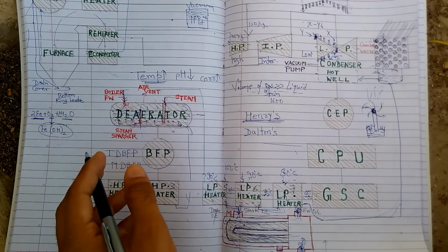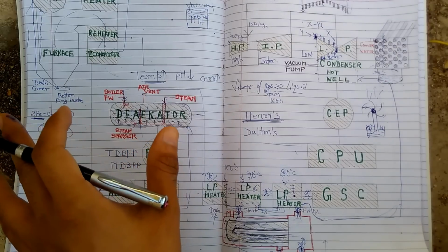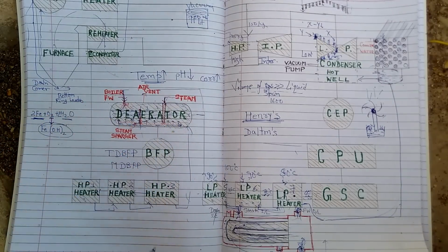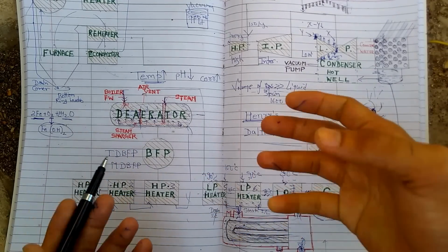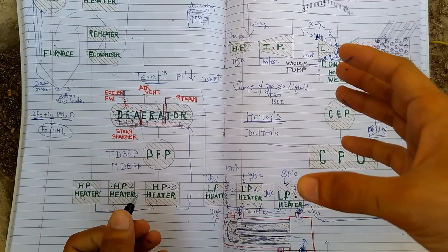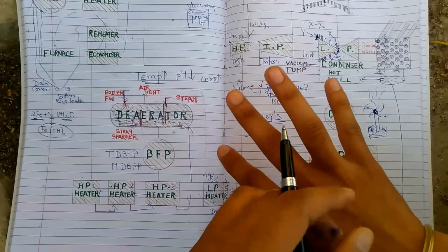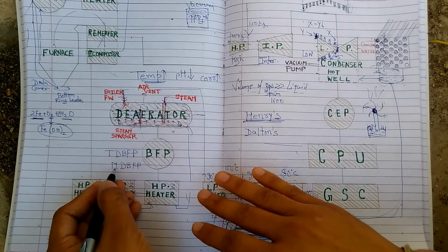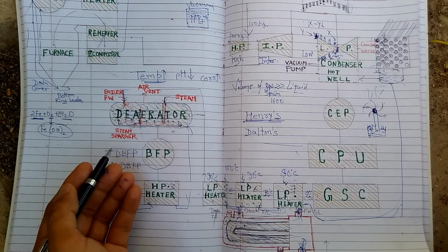Now I have this boiler feed pump. It is the single entity resulting in maximum auxiliary consumption in a unit. It may consume up to 10, 11, 12, 15 megawatts of power. That is equivalent to supplying a town. Okay, so what we see nowadays as a trend is TDBFP instead of MDBFP. MDBFP is motor driven boiler feed pump. TDBFP is turbine driven boiler feed pump.